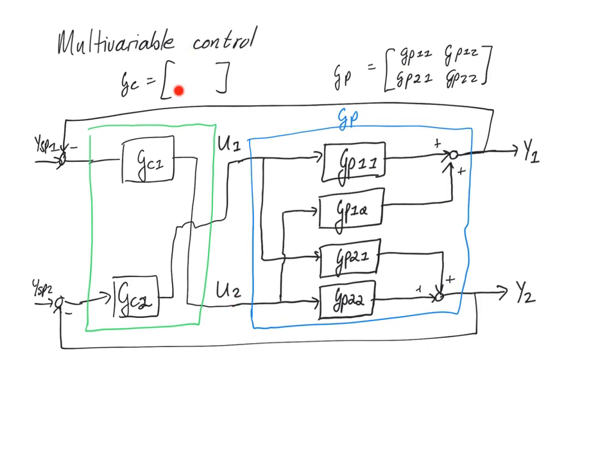And remember that we can associate the columns of the transfer function matrices with the inputs and the rows with the outputs. And so we can ask ourselves, the first input of this matrix is connected to the second output. And so therefore GC1 must be in this off-diagonal position over here. So that's the first input and the second output. The same goes here for GC2. And there are no connections between the first input and the first output, or the first or second output and the second input. And so we end up with this block diagonal form.